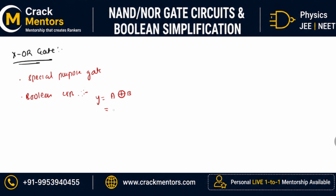What does that basically mean? This means A B naught plus A naught B. Got it? A B naught plus A naught B. Now I think you can guess what the XNOR gate is. XNOR gate, if I write it side by side, is equal to the opposite, the inversion of the XOR gate.